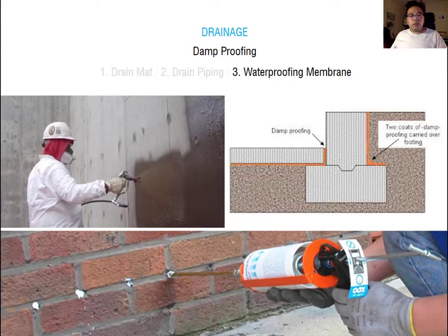So when you're designing the retaining wall on the bottom, or connecting the joint between the floor and the wall, you always have some joint between. Even a very small gap lets moisture and water easily come into your place. Okay, so this leads to condensation and moisture loss into the basement. That's why you have to protect very well between the components through this gap here.